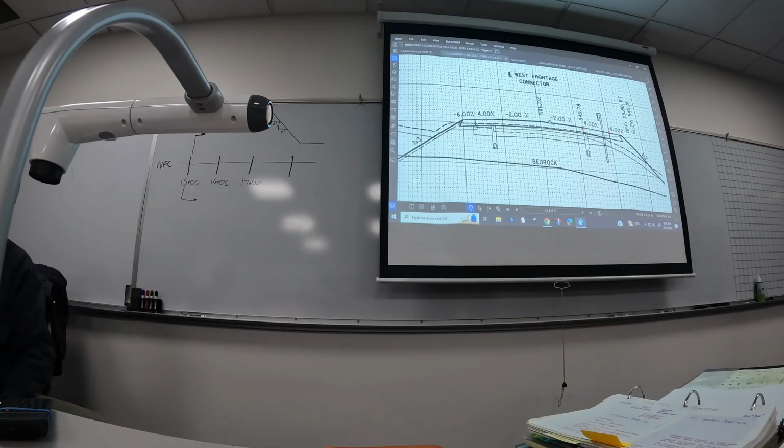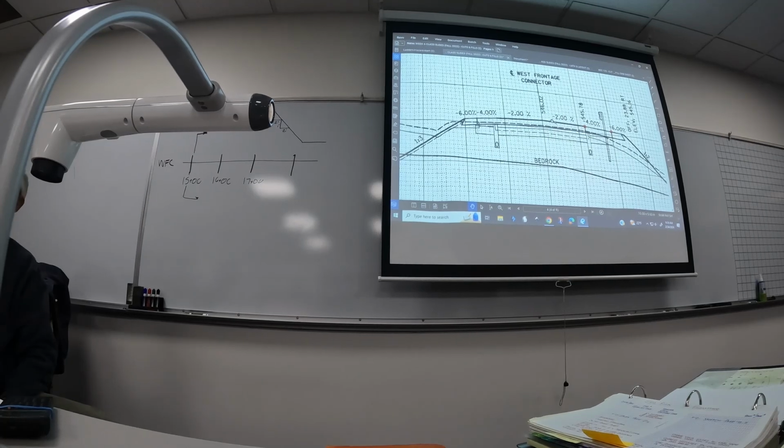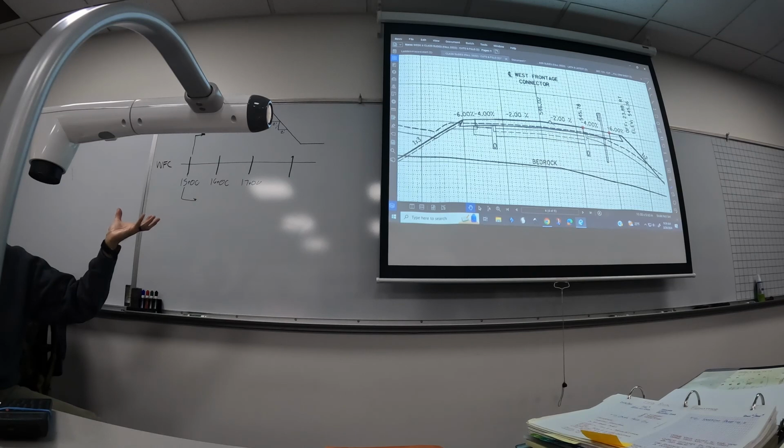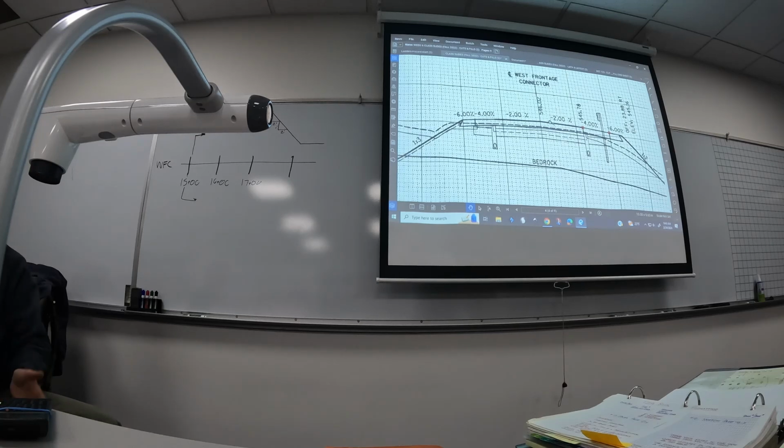So like when you see a dozer or something, you'll have a surveyor, basically he's got the stick with it looks like a plate. Mm-hmm. If you look on their blades, they have them on each edge. You got it. It's all talking. Yeah, the GPS receivers now can sit on the tips of the machine. Sometimes they're on the top, but that basically is just doing the same thing as what a GPS instrument is doing. It's bouncing off satellites, it's reading things in real time, and it can make the adjustments. If the three-dimensional model is built and then put into the computer system in the machine, it now can go where it needs to go.